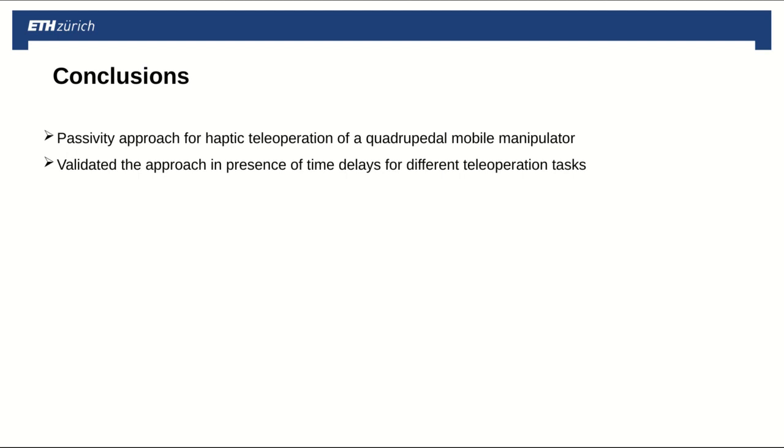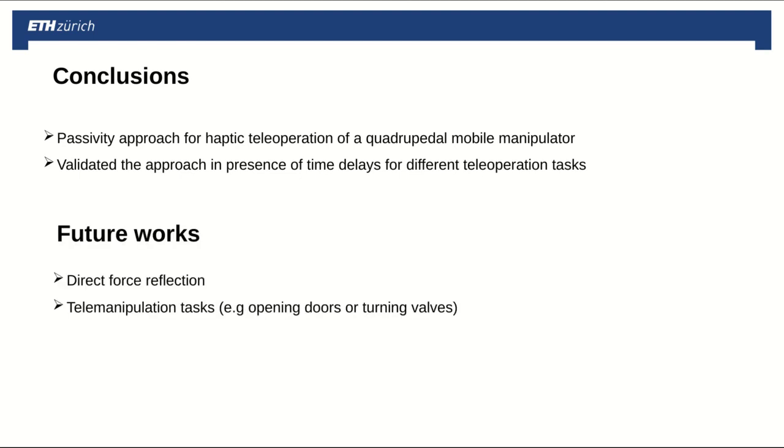We presented a passivity-based approach for haptic teleoperation of a quadrupedal mobile manipulator. We validated the approach in presence of time delays for different teleoperation tasks. And in the future, we could implement a direct force reflection approach where we feed back the force measured at the end-effector with a force sensor, and we can extend the approach to perform more telemanipulation tasks like opening doors or turning valves.